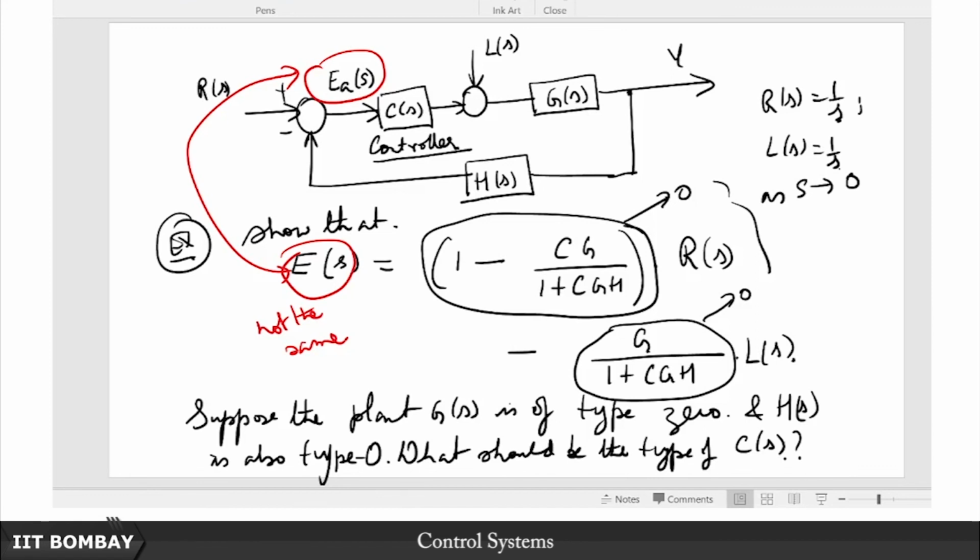So in order to do that, we have to basically keep track of the number of closed loop poles that are in the RHP and the number of closed loop poles that are in the LHP, left half of the complex plane and the right half of the complex plane. If all my closed loop poles are on the left half of the complex plane, then my system is stable, and such polynomials are called Hurwitz, and that is for a reason, because it is this Routh-Hurwitz criteria that we will study next, and these two gentlemen, Routh and Hurwitz, basically gave us this method to discern as to whether a given polynomial has all of its roots on the strictly open left half plane.